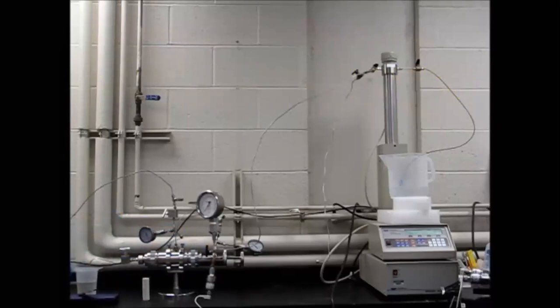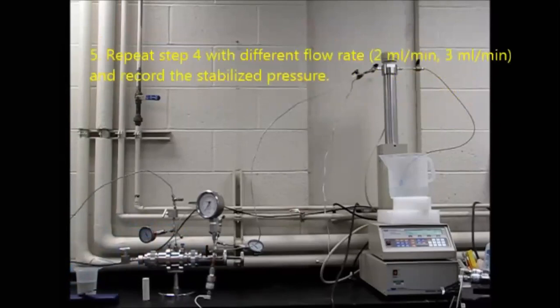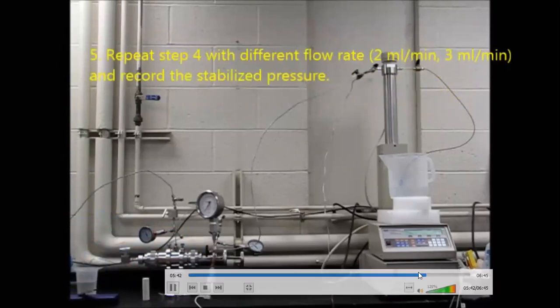Then whenever the pressure is stabilized, we will record P1 and P2. Then number 5, repeat step number 4 with different flow rates, which is the flow rate to record, and plot.